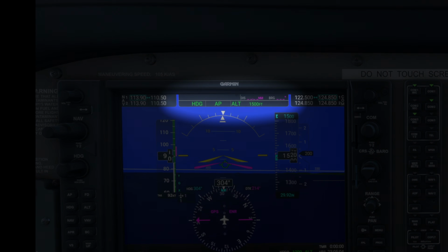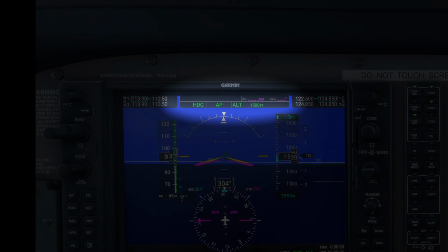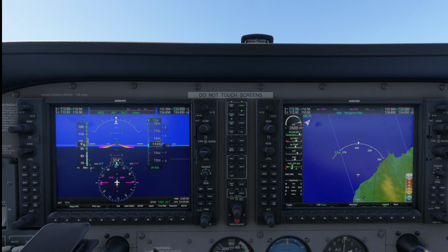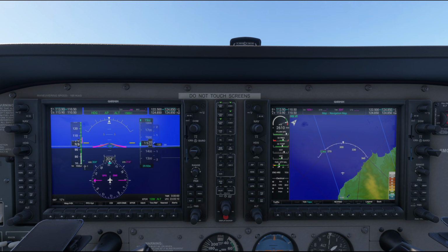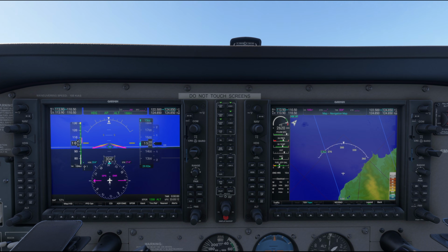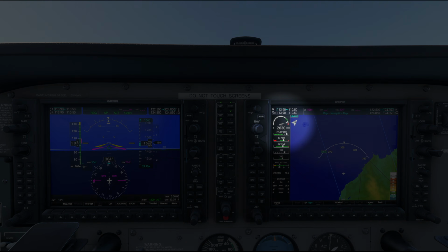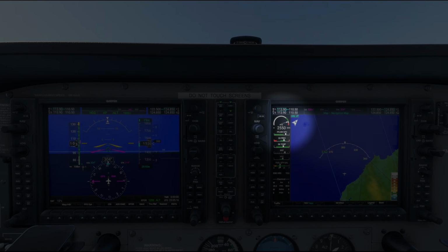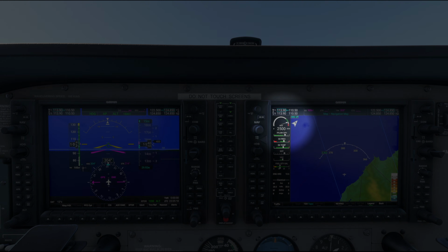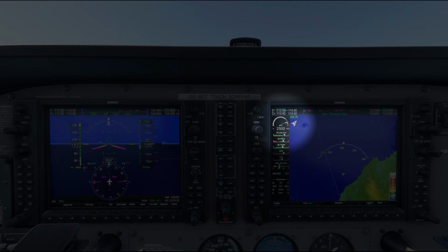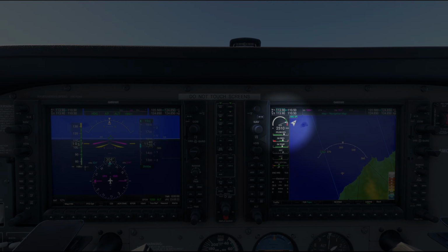One important thing to note is that autopilot is not controlling the throttle, so the way it controlled the airspeed in the climb was by adjusting pitch. We still had to set full power on the throttle. In cruise, in a real aircraft, you typically want to keep the RPM at the top of the green arc or less to avoid excessive engine wear. So after we level off, we need to bring the throttle back a bit.